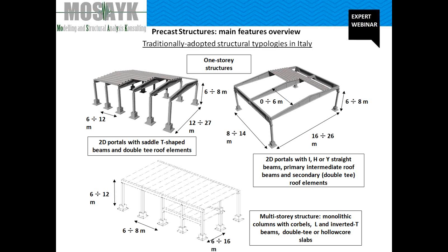due to the fact that the columns are fully continuous starting from the socket to the top of the roof. The plastic hinges are for sure expected at the base of the structure, except for particular cases such as sudden interruption of the longitudinal reinforcement along the height of the column.